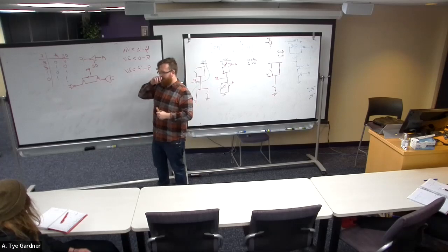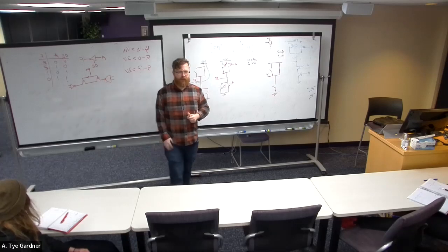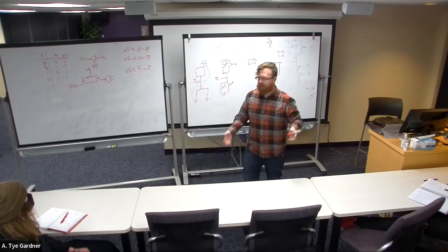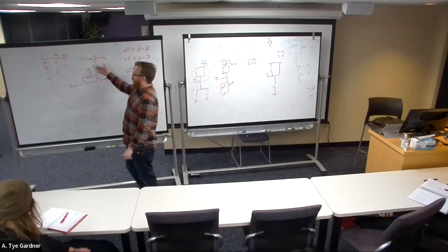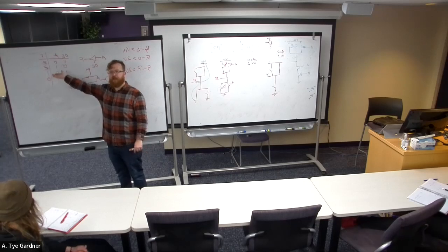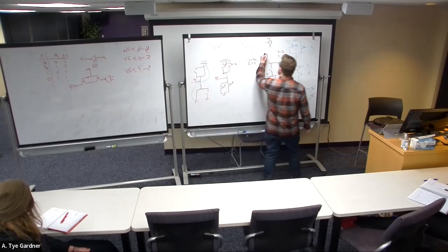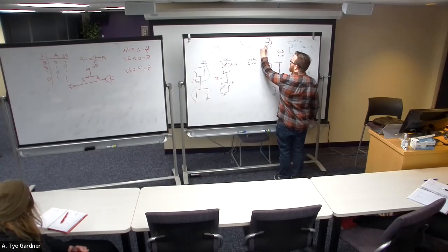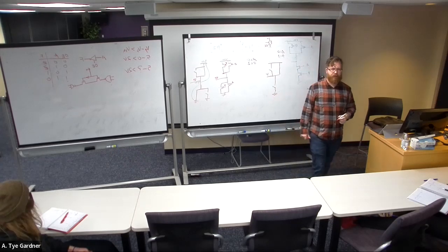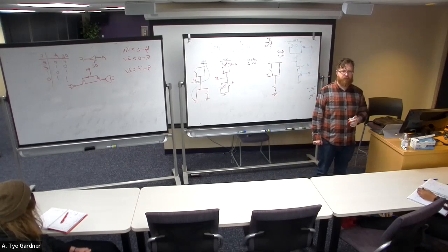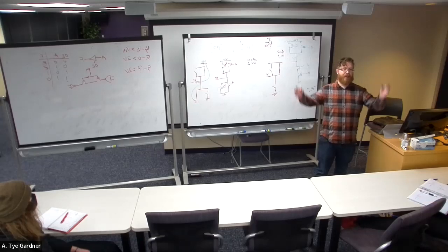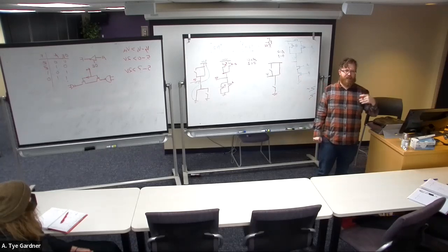There are other ways to build it. There are certain situations where doing it that way won't work. You don't have to worry about the details. Mostly, I want you to keep in mind that output enable has this truth table. We could even have output enabled NAND gates. It would be just a NAND gate with another pin called OE, output enable. It just causes some of the outputs to just disconnect. This goes to high impedance, which means just pull the plug, like an open switch, right? Which means it doesn't see it.